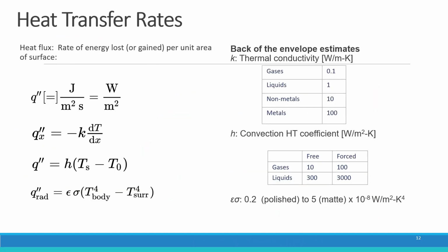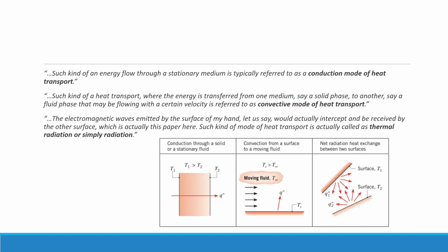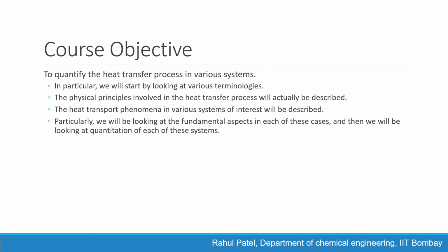So yes, in conduction we use Fourier's law, whereby the heat transfer rate is directly proportional to the temperature gradient, and also is dependent on this K. The same thing I can write in terms of the driving force, that is delta T upon resistance. So we calculated this resistance using the resistance concept in week 1.